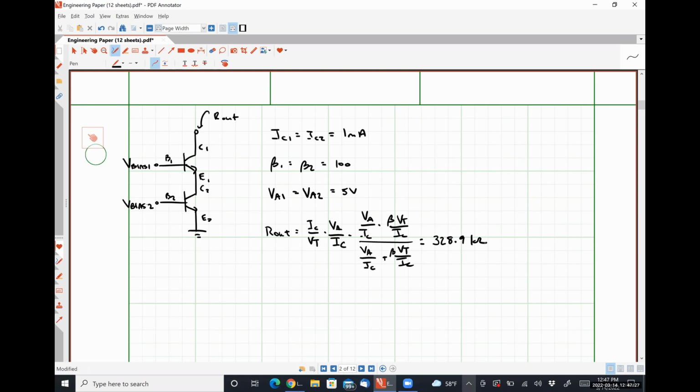Okay. So with this cascoding, one of the biggest advantages is that we get extraordinarily large output resistances by doing this. That is exactly correct. We use this to increase gain, and it's got a lower hit on headroom.